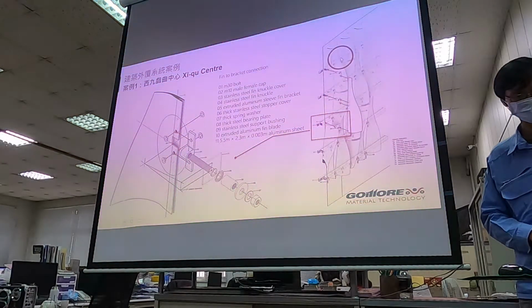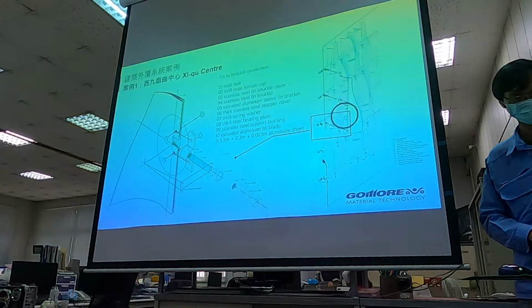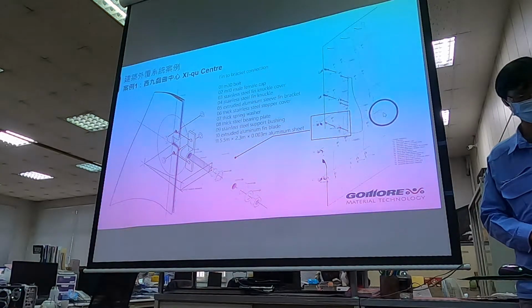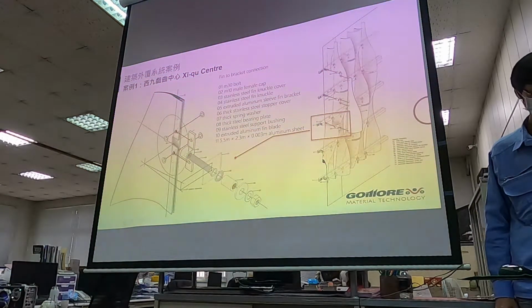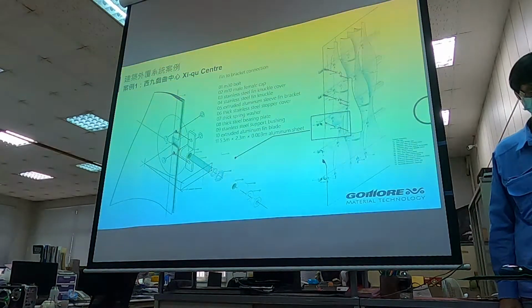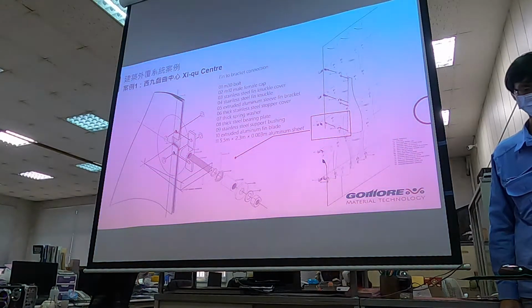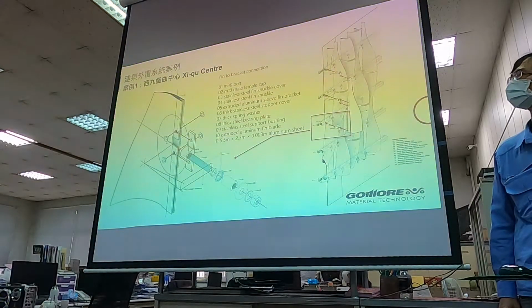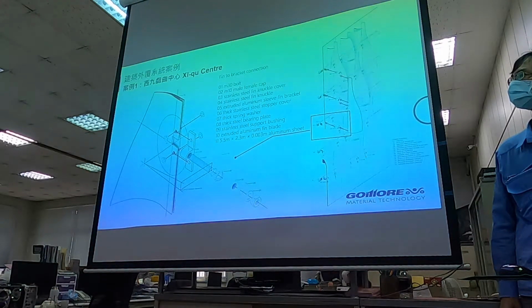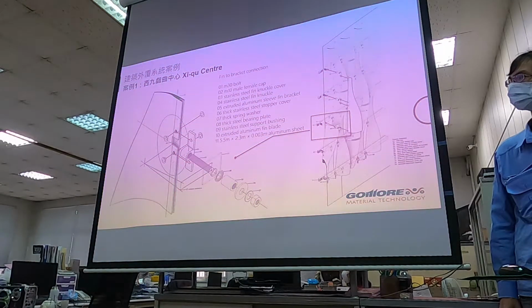So all the shaping is pre-designed in 3D programming, and you make it panel by panel in sequence, and then you install it onto the wall. We call this a decorative facade because the system itself provides the function of a rain screen. It's not airtight and watertight, so we call it a decor facade.